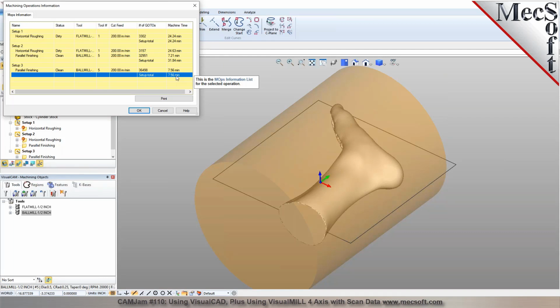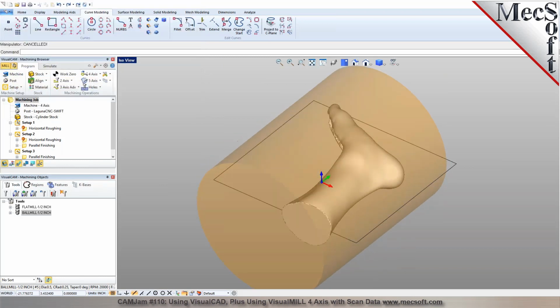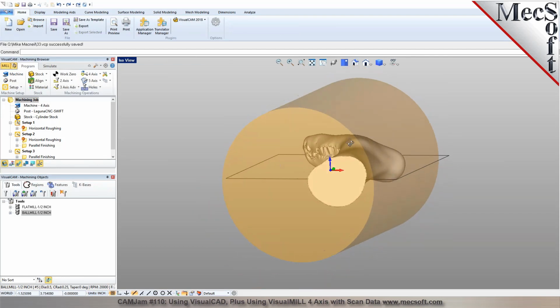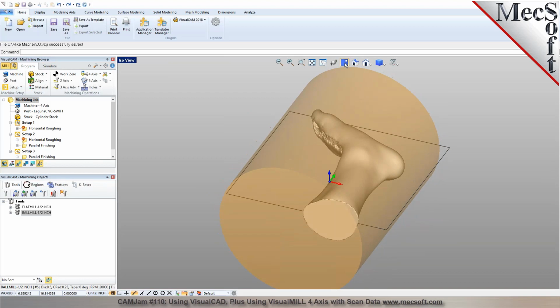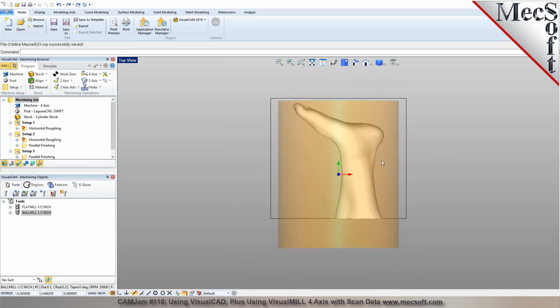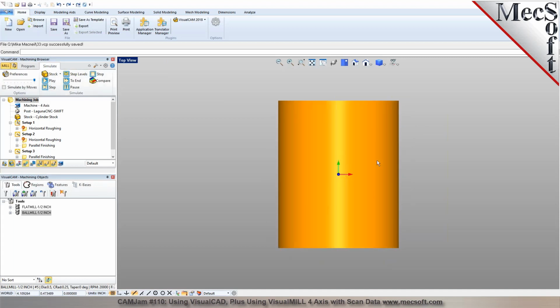Okay, there's one thing I would like to point out. If you'd like to do a continuous finishing where the part is rotating as you're cutting it, then we need to make sure that the entire part is through the rotation center. In this particular case, it would be off center because this is your stock blank in here.